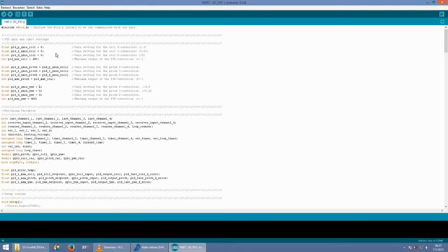For now, we set a P gain of 3 and an I gain of 0.02 for the yaw. This basic setup will prevent the multicopter from yawing when we try to fly it. You can raise these settings later on. Setting a D gain for the yaw is not necessary because the yaw has much drag from the props.